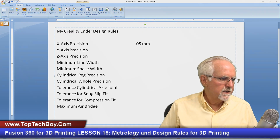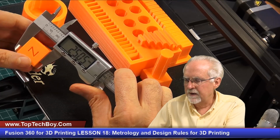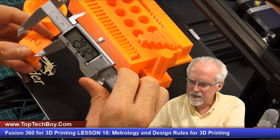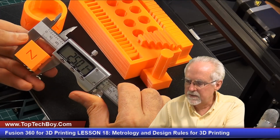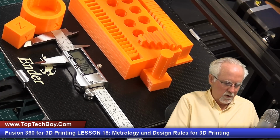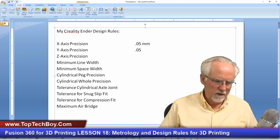Let's come back over and look at that in the y direction. So I'm going to look at this along the y-axis. 25.04, look in a little different area, 25.05, a little different area, 25.06, come in differently, 25.06. And so again, something very accurate to say is about 0.05 millimeters. So I'm seeing my behavior along the x-axis and the y-axis to be within 0.05 millimeters. Got to make sure I'm getting a good view.